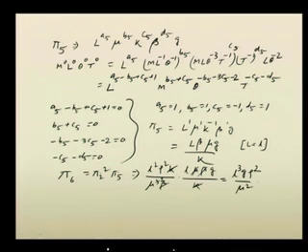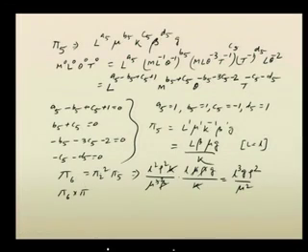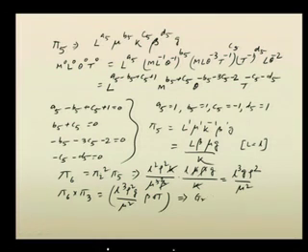Now, if we couple again that pi 6 into this one, pi 3, then we get L cube rho square g by mu square into beta into delta t. This whole expression is termed as the Grashof number. So, finally, I can say that this is equal to, say, pi 7. So, all these things together.